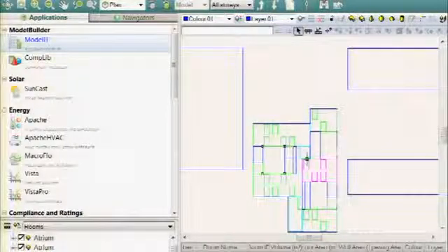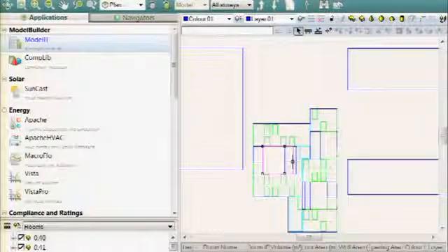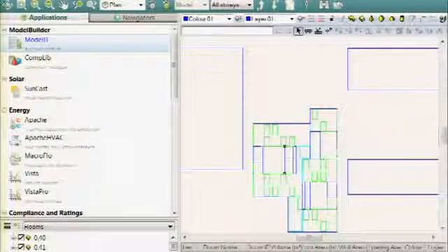And then what I can do is come in and say, all right, there's one room that's probably causing this issue because I can see it's actually surrounded by 6 rooms on each side of it. So what I do is I'll delete that center room and redraw it, see if that solves my problems, and rerun my checks. But that check right there is going to be the key to telling you if you're going to have an issue when you run it or not.